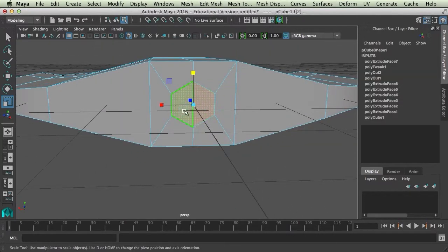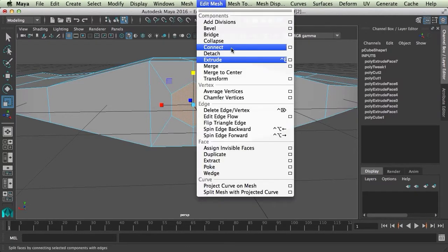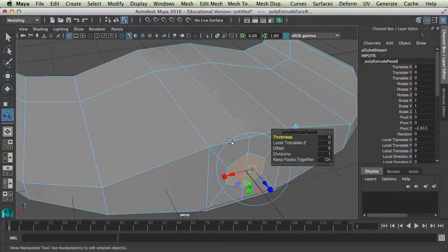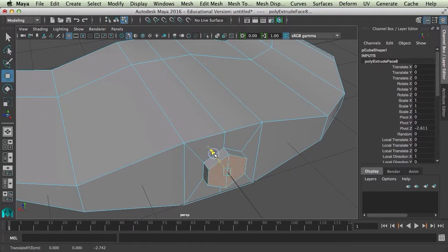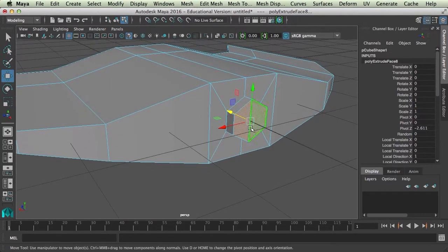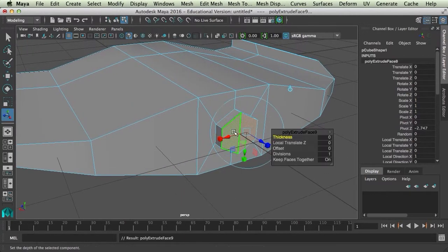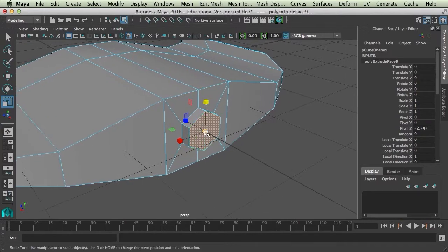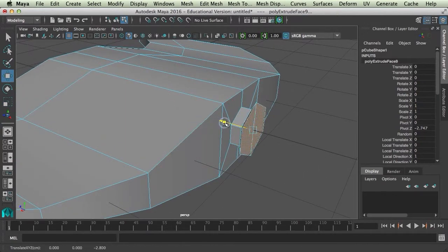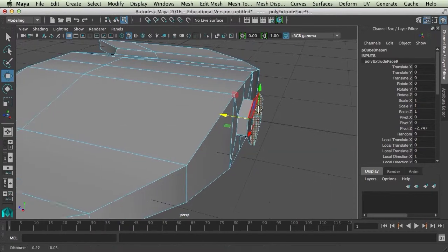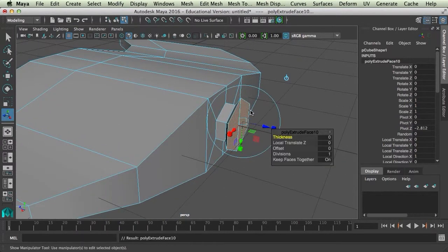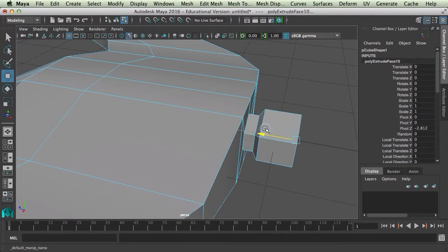And then when I extrude these faces out, I have something that's more round, and that is good enough for me to pass off as round. I'm going to continue extruding this out. Let me scale this up. I'm going to move it out slightly, so I have that little lip where the engine's going to start. Extrude again, move this back.